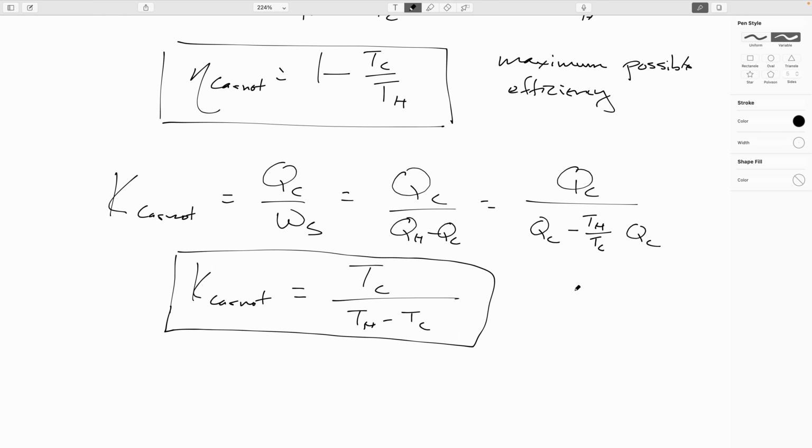But with a heat pump, which is an air conditioning system that's designed to run backwards to move heat from outdoors to indoors, you can have coefficients of performance that are greater than 100%. You can move more heat than the work it took to move it. Now, the limit on this is how cold it is outside and what the difference in temperature is that you're trying to maintain. At first, this may look awful, but keep in mind, these are absolute temperatures.